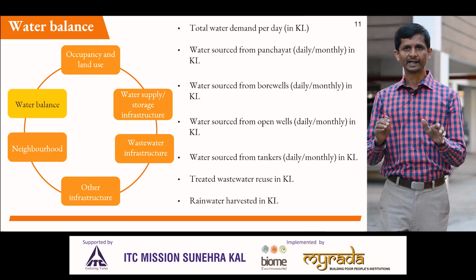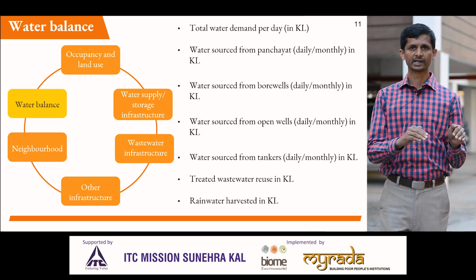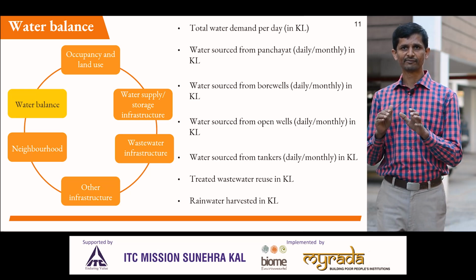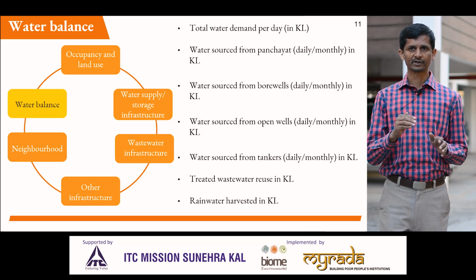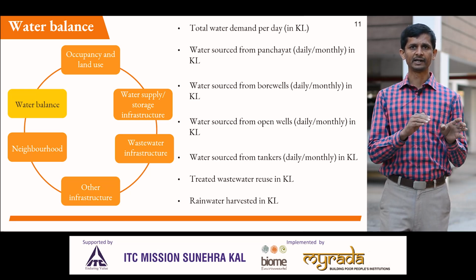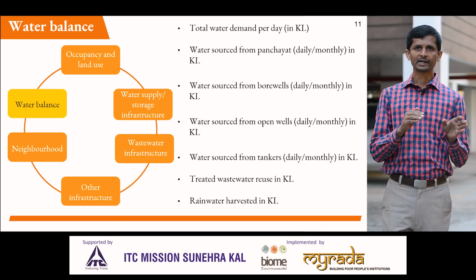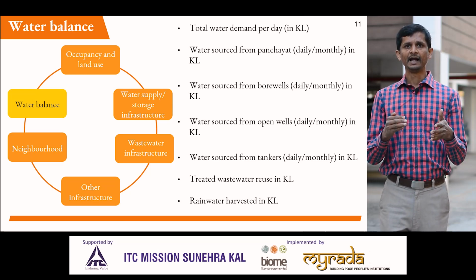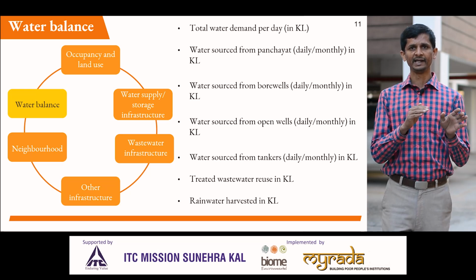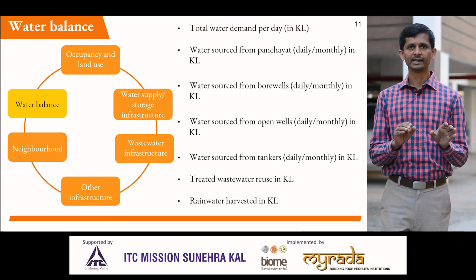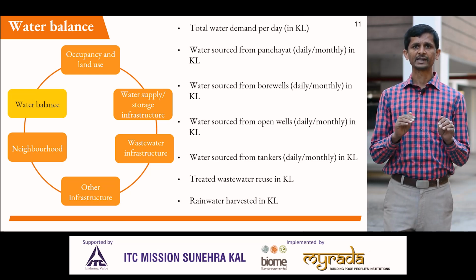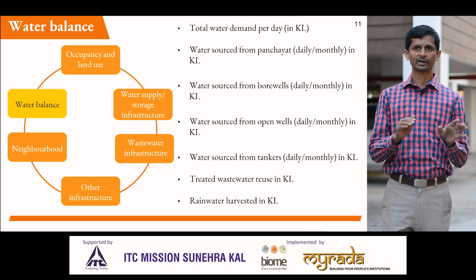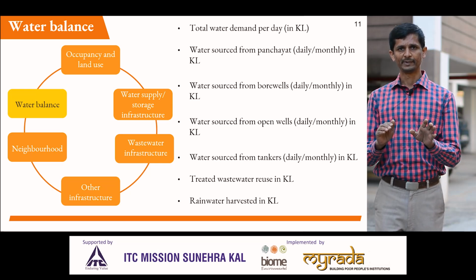Calculate your water demand, water inflow from different sources, any rainwater harvesting infrastructure for storage and recharge, the outflow of treated wastewater and how it is utilized or disposed of. What is the water scarcity at present and the water scarcity anticipated in future when the occupancy increases. Your water balance depicts how sustainably you are managing the water inside your apartment.